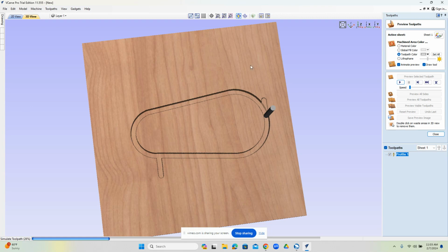But really, there's a couple of ways to do this. Number one, you have your lead settings, so you can change your lead location. I really would recommend not even using a lead, just plunging. I think you should be able to resolve that. If it's burning right at the plunge, maybe slow the plunge feed rate down. The other thing is this straight in and straight out move on the lead in that we did. This I think would be maybe a better option to kind of work its way into the profile, work its way around, and then exit.